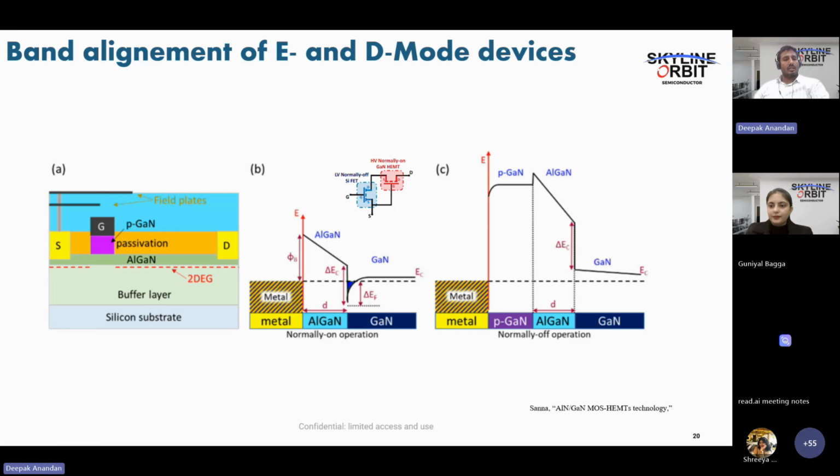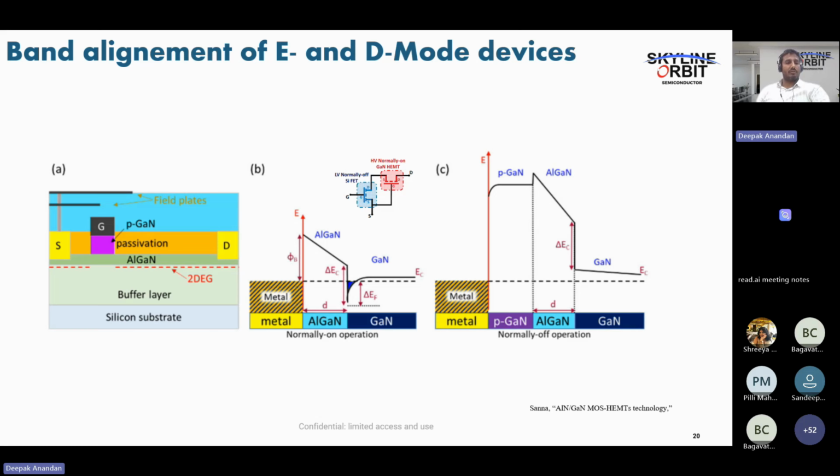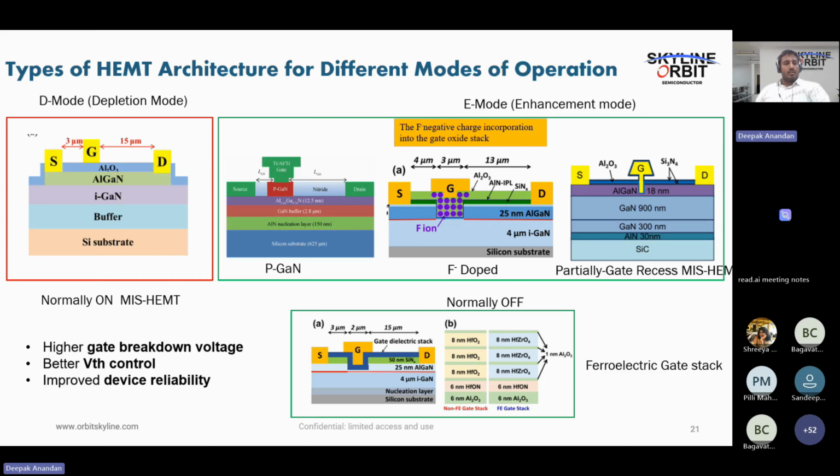To avoid gold intermixing or contamination in the CMOS fab, you need to separate the line for metallization and other steps. For the rest, about 70% of the process flow can be done in the existing CMOS fab itself. This is another current trend, that companies try to utilize the CMOS fab for gallium nitride technology as well.